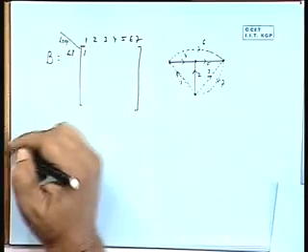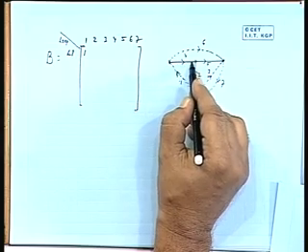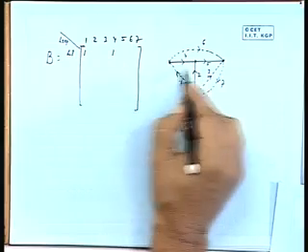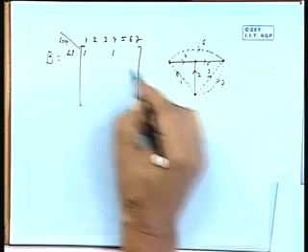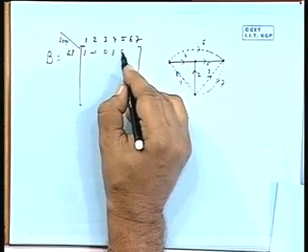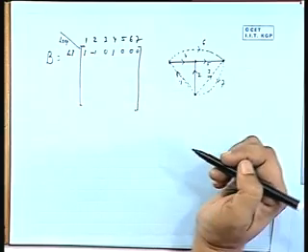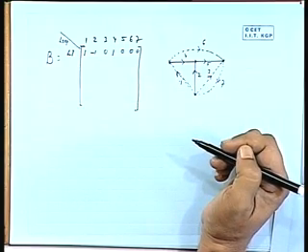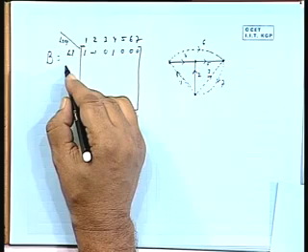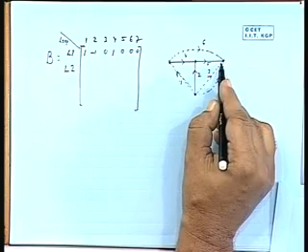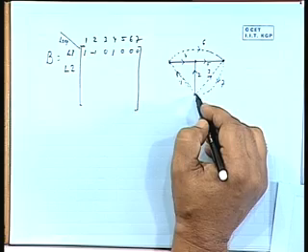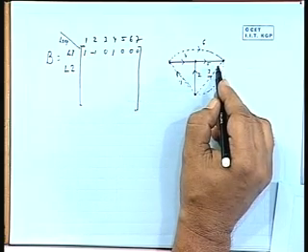So if it is in the opposite direction, I will put a -1 sign. If it is in the same direction, I will put a +1 sign. So here, element number 1 will be 1, element number 4 will be 1, element number 2 is -1, rest are all 0, no other element will be connected with this. Is that okay? Then loop 2, I can choose the second link as this one, then this will be the direction because the direction of element 3 is this.